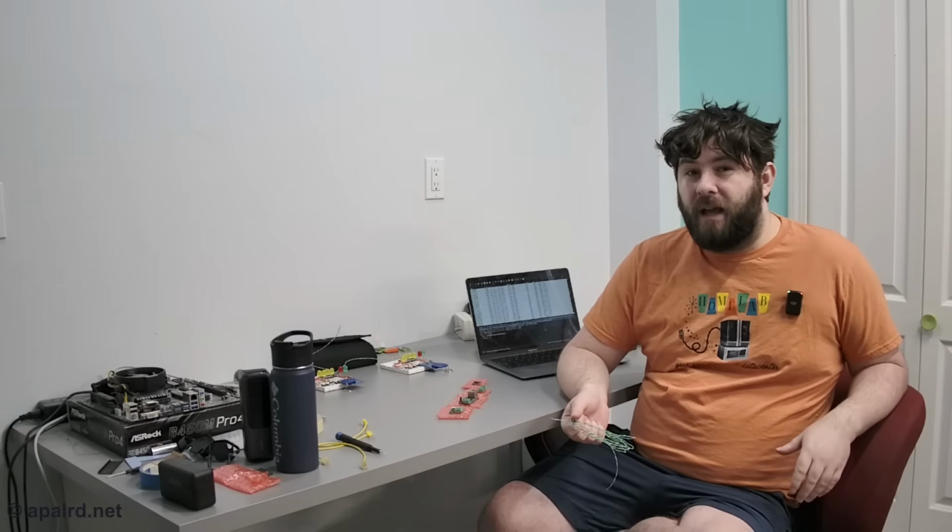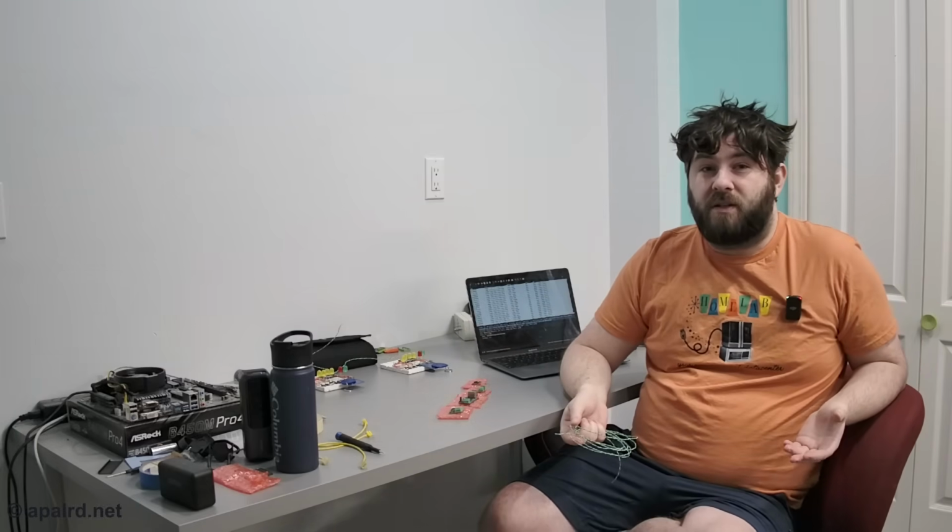But then on chassis CAN, we have stuff like the engine, transmission, transfer case, active suspension, adaptive cruise control, all of that. And notice that on both of these buses, we have components all around the car. So both of these buses have to run front to back, side to side, whole length of the car. That's essentially twice as much twisted pair because we have body CAN and chassis CAN running across the car. As we start moving to higher speed buses, it gets even worse. We have gateways all over the place.